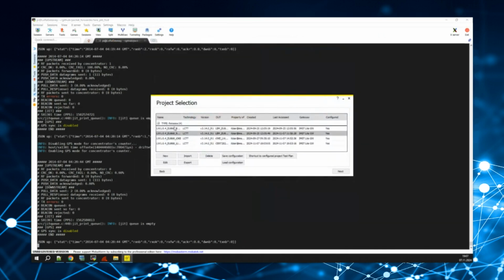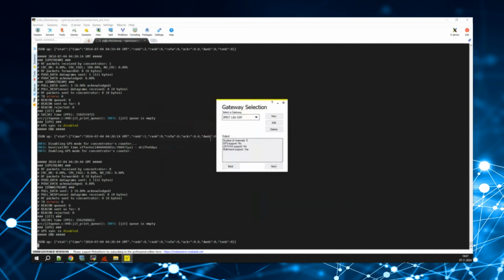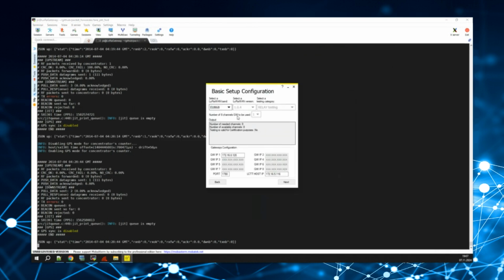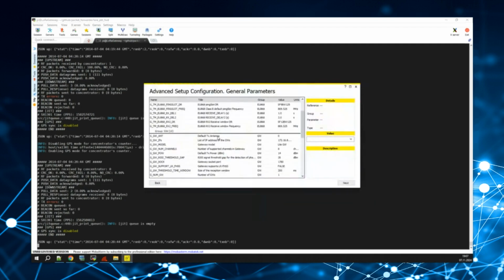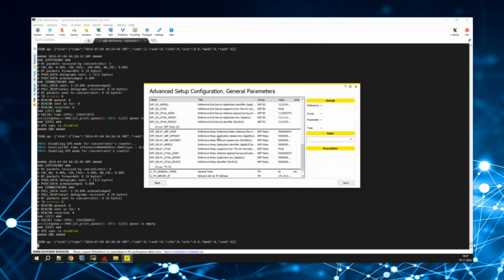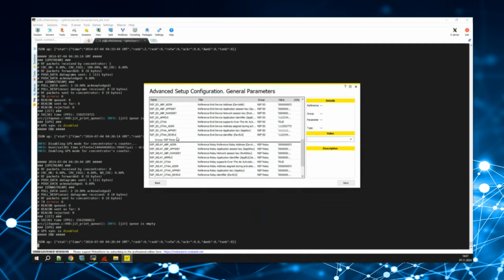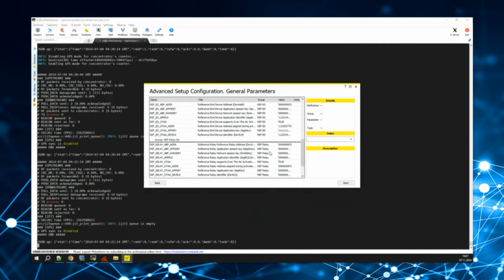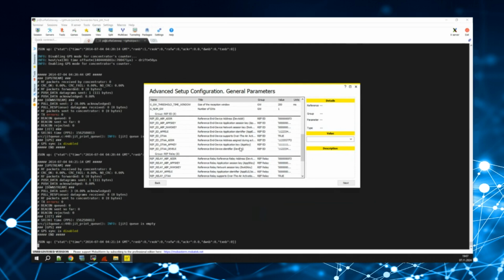In this case, one important thing is in case you are running the relay testing. So we could see this is a different setup, a special one. So here you need to select the relay testing. And in case you are testing an end device, you will need to configure here the reference relay activation parameters in order to be able to activate the relay and to gain communication with it.